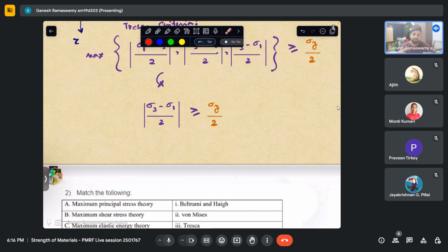Because we generally take a rod of steel, let us say, and then we will be loading this in the universal testing machine in order to determine our sigma y. Whereas the same structure, if there is a structure made of steel, we are extrapolating the material properties of this rod to the actual structure. So there is some approximation involved.